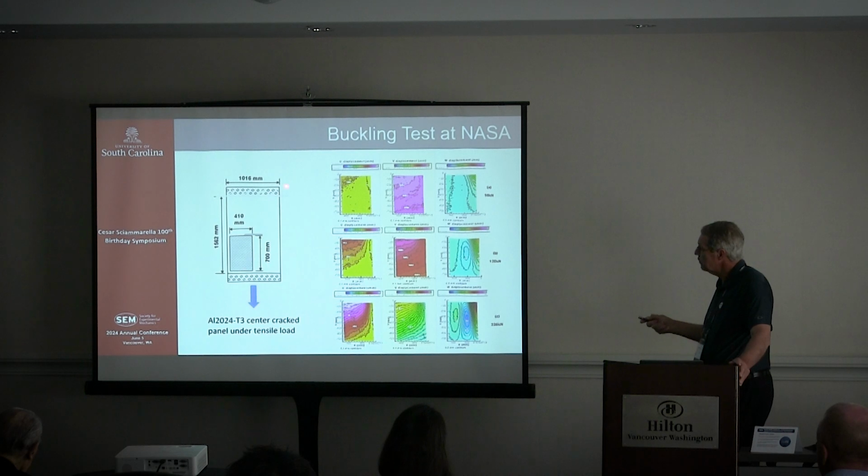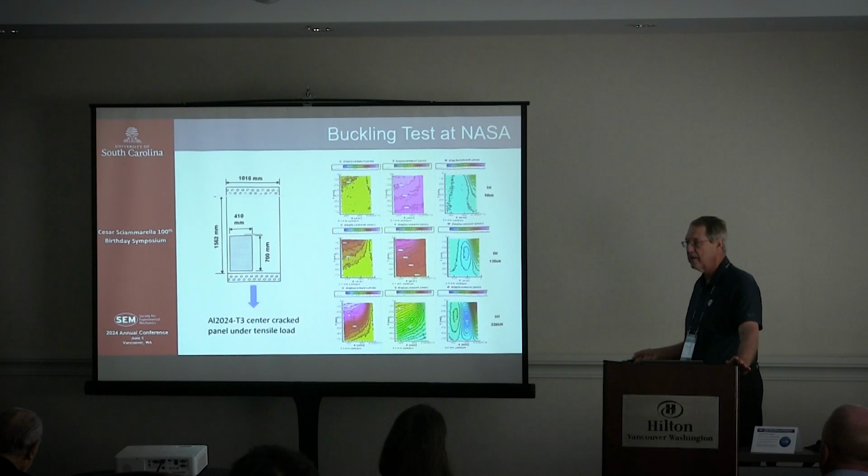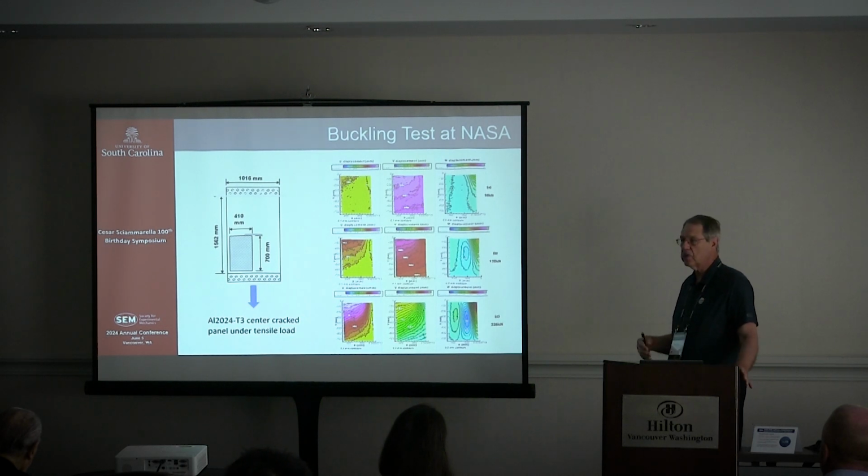Look at the V displacement, which is vertical. And what you see is the lower grip area, which should be flat, it should be straight across. The displacement should be the same everywhere, even for the lowest loads, was not. So something was happening at that point. It got worse as the loads went up, and at the bottom you can see there's a large scale displacement of one side relative to the other, which means it's rotated. It's either slipped out of the grip or something has happened.